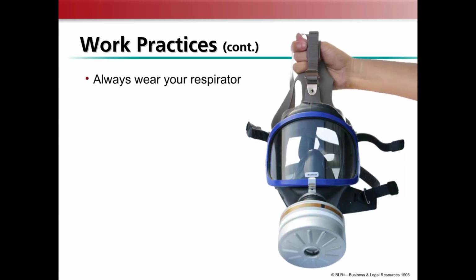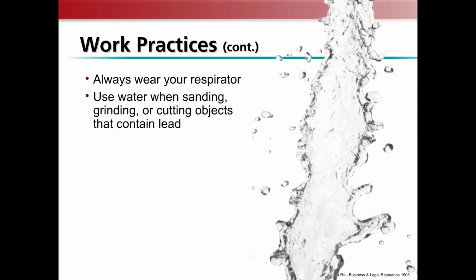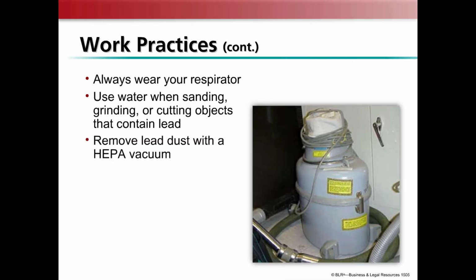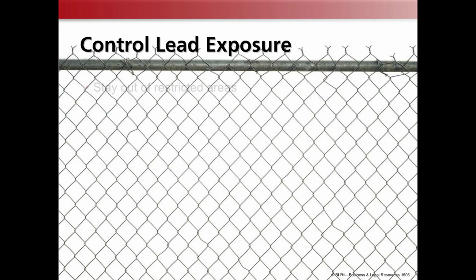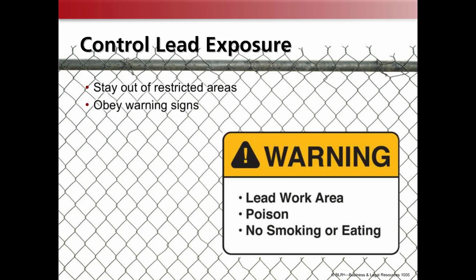When working in a lead area, always use your assigned respirator. Use water when sanding, grinding, or cutting objects that contain lead. Use vacuums with HEPA filters to clean floors and other surfaces. Do not use compressed air. Do not shovel, brush, or use dry sweeping. Stay out of restricted areas unless you are authorized to be there. Obey warning signs. Signs should state, "Warning, lead work area, poison, no smoking or eating."